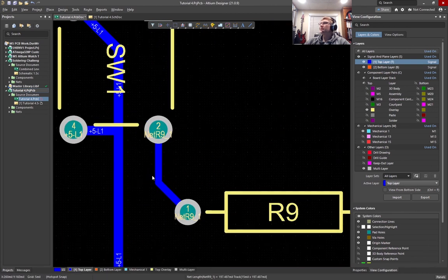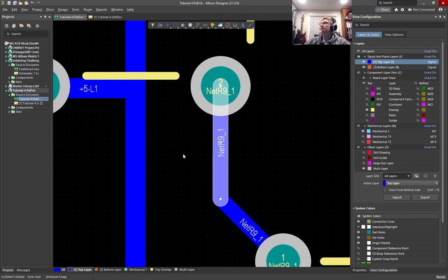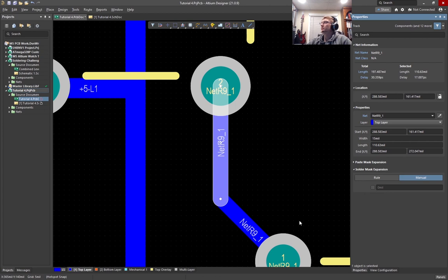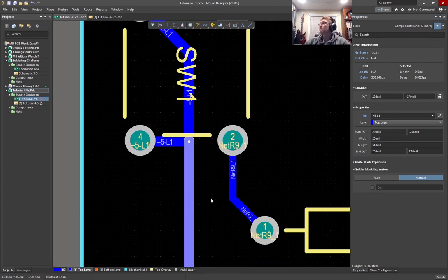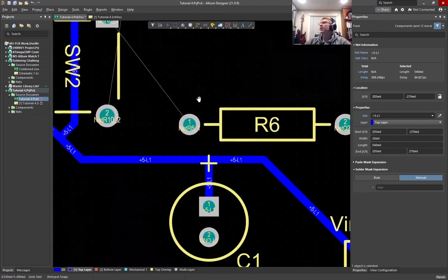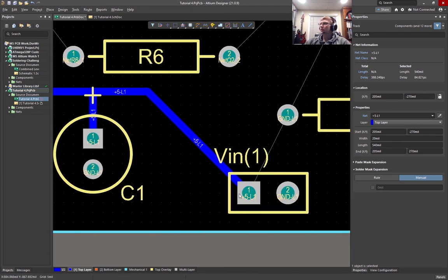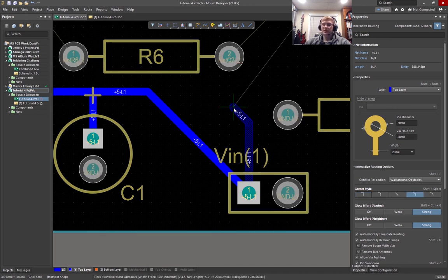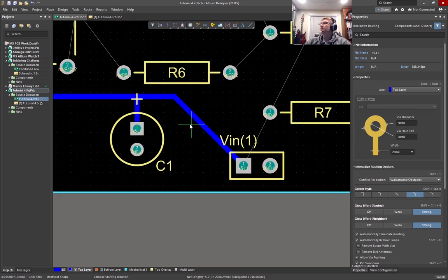So you're going to see that those automatically draw at a different width because remember we set a specific scope for two different rules. So now this rule is going to have a 15 mil preferred thickness as opposed to the 20 mil preferred thickness. Actually, I think it was 25. Yeah, like I was saying, when you go to route things, once this is down, if you press 3, you can cycle through your thickness settings from your rules. So right now these were set to 20.